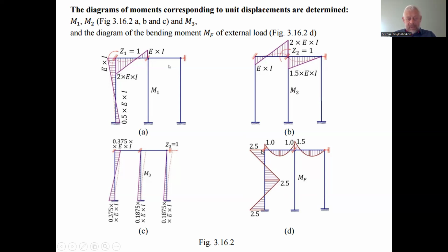When we divide the assigned mechanical system into the set of single span two supported beams, statically indeterminate, we can use the previously known solutions for other kinds of supports and load distribution for the single span supported beam, the standard solutions from the directories and from the textbooks.